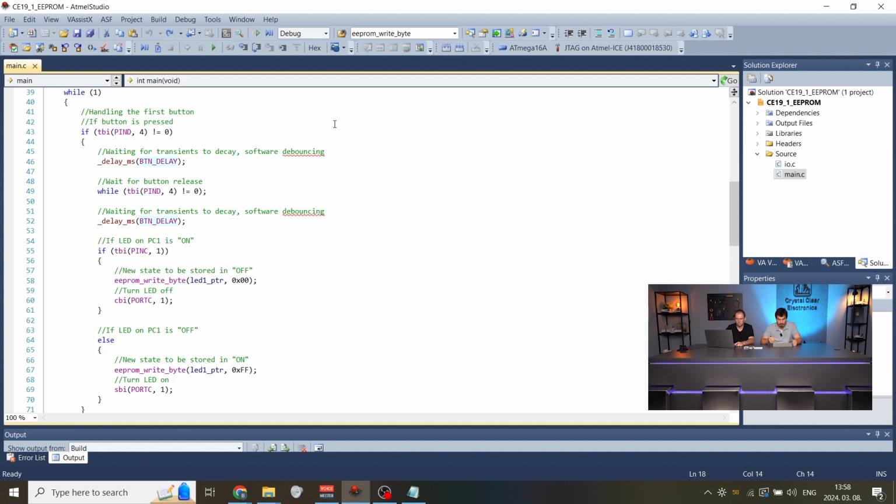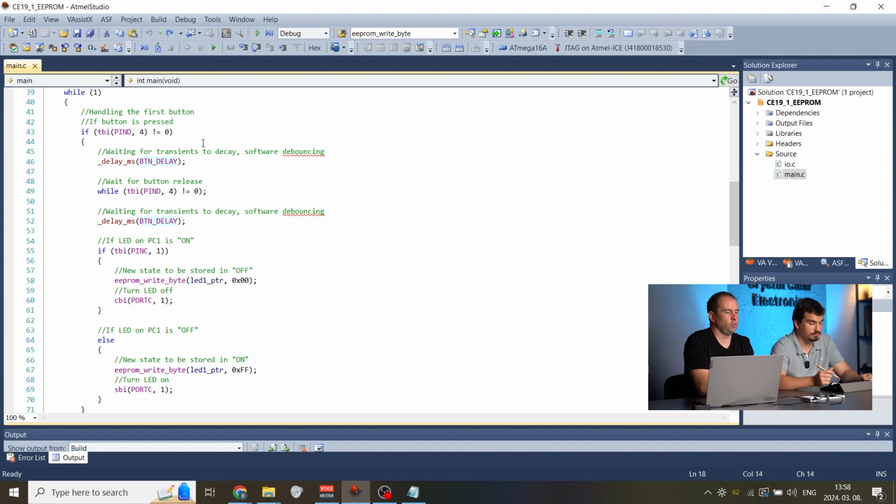The system reacts to the three buttons separately, but in a similar way. The only difference in the rest of the code compared to the section above is the EEPROM address and the pins. We enter the first if when the button on PD4 gets pressed and pulled up to logic high. We did not implement hardware debouncing for the push buttons, but we still want to avoid the negative effects of bouncing, for example unnecessarily writing the EEPROM at every edge, wearing it out. Instead, we have to implement debouncing in software.